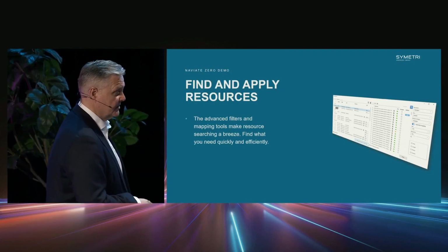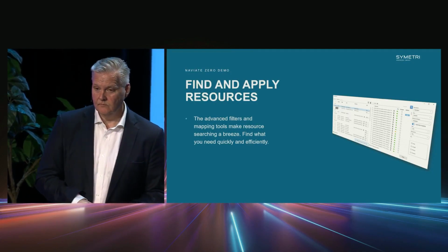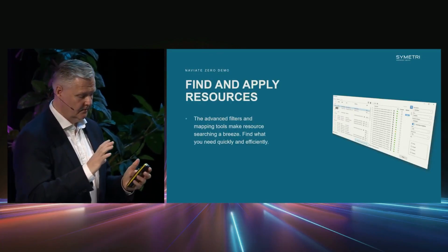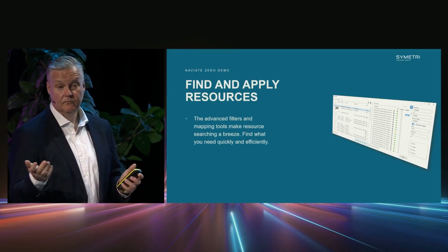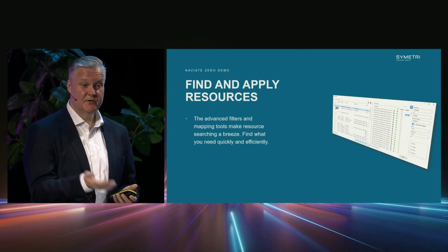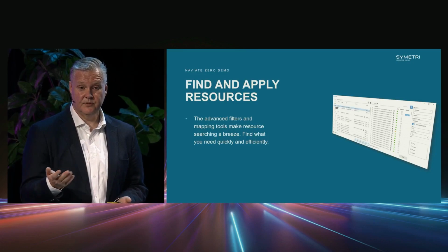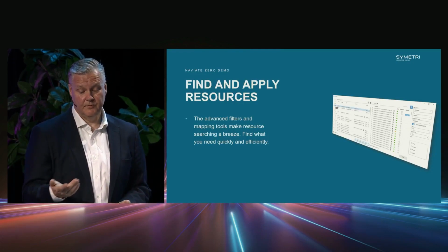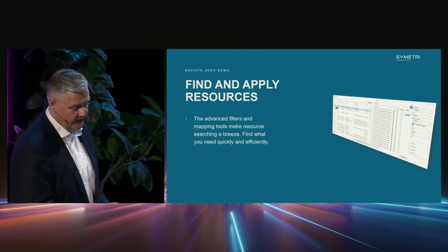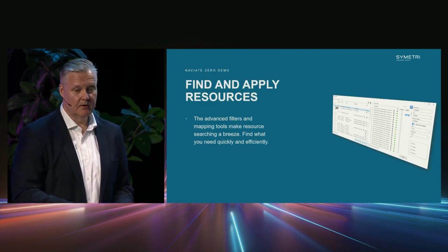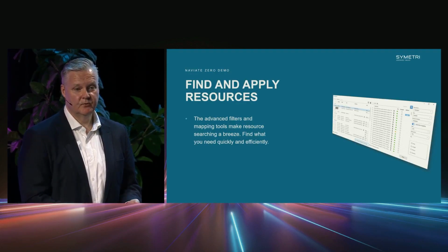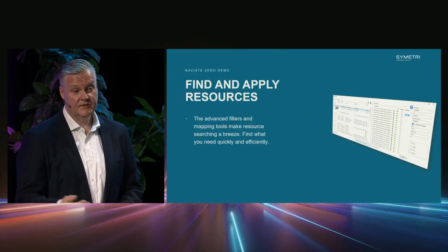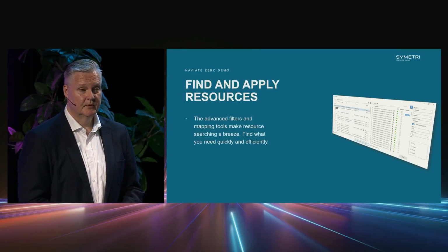Resources. Are you working with steel, timber, glass? Pick those. Make sure that you have a focused area to work on. Then, are you in early phase? You most likely are using generic EPDs, not manufacturer EPDs. So you can also choose if you would like to work with generic EPDs or the manufacturer ones. And of course, if you only would like to consider the best CO2 resources, you can pick those as well, or even see what's the worst one.